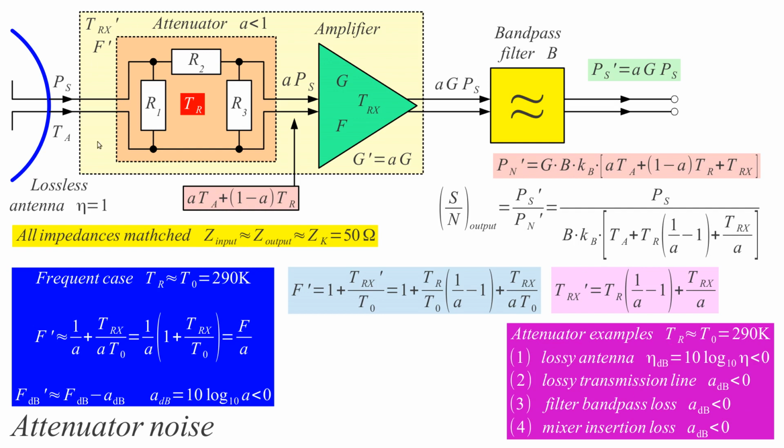We didn't discuss this thing yet. So we may have frequency mixers. Frequency mixers may be active, maybe passive mixers. In the case of passive mixers, they have a conversion loss that also translates into insertion loss here. What is the calculation now here? We have an attenuator in our line that is going to attenuate our signal by this factor A less than 1, or negative dB here.